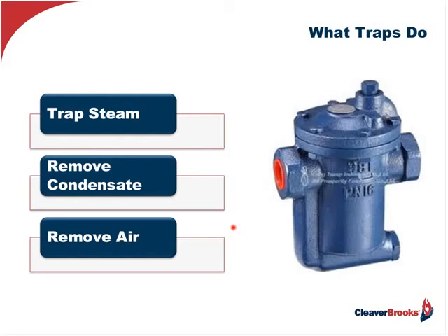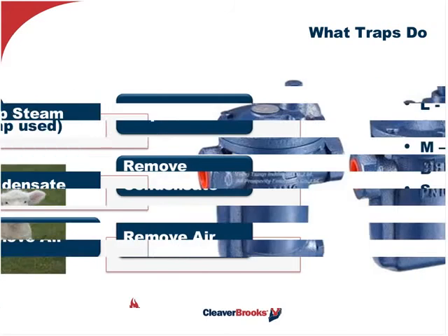At various bends, there should be vents. At low spots, there should be vents. We want to get rid of that air because it's very, very corrosive, and we'll talk about that. The trap itself will not get rid of all the air. So how do I select a trap? Well, first of all,